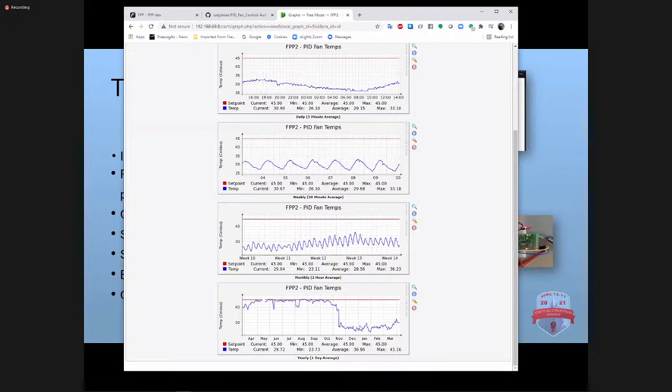Say, for example, I've manually turned my fan on in November, so it's been on in this range. But during the summertime, you see it's getting up there and it's regulating. Some of the time it's dropping down a little bit, but it's mostly regulating. But if you could see over time, maybe all of a sudden something happened. Maybe you had something break loose inside your enclosure and jam your fan. You could see when that happened. In addition to the plugin telling you that your fan had stopped turning because it's going to get an RPM fault, and you would exceed your temperature, so you get a fault on that as well. But you could see historically when that happened if you were monitoring the device.